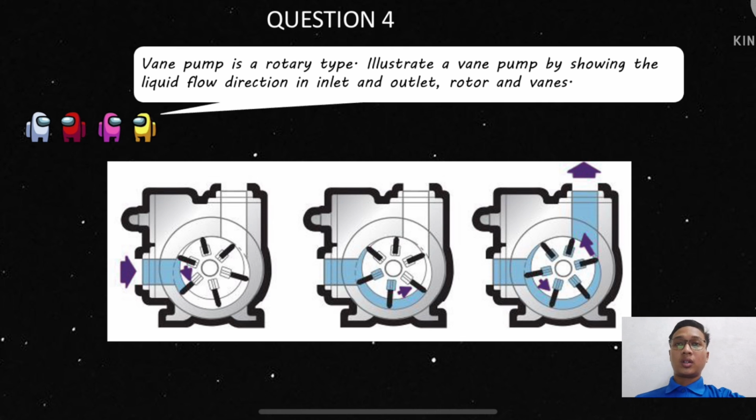Second, the housing of the cam allows fluid into the pumping chamber through a hole in the cam. Fluid enters the pocket created by the vane, rotor, cam and side plate.